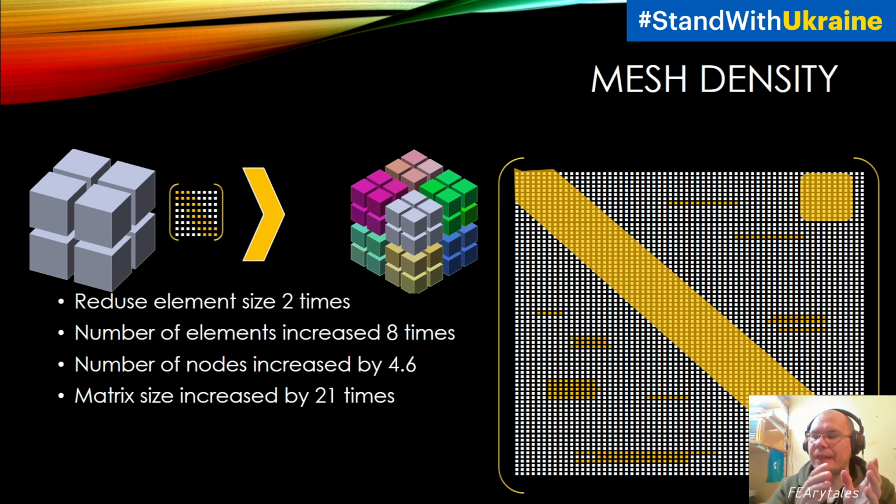So if you have the same mesh with the same density from linear tetra and from quadratic tetra, you will have a difference in size of the task 2 times, and you need a different volume of resources. For quadratic tetra, you need 2 times more. So it means that you can reduce the size of linear tetra and create a finer mesh.